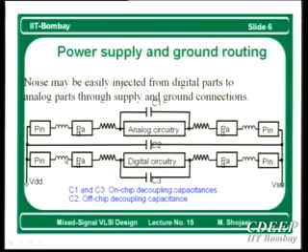And this drop is not a constant drop. It just depends on the switching. Therefore, you will see this bouncing on the VDD as well as the VSS line in a digital circuit. And the analog circuit is almost quiet. Therefore, this is one of the problems.